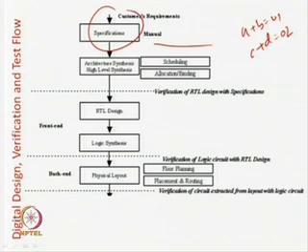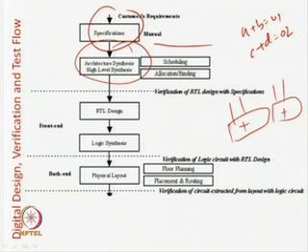Next, we go for an architectural specification, called high level synthesis. In this case we will take an elaborate example, and we will elaborate it in the following slides. Architecture example means you will take two adders, with A, B, C, D as inputs and the two outputs. This is at a very broad level. Now, this is operation 1, this is operation 2, so we require two adders for that. Then you have to answer questions like whether this adder will be allocated to this operation and this one to the other, or vice versa. Sometimes we can also say that two adders are not available, and a single adder will be there.